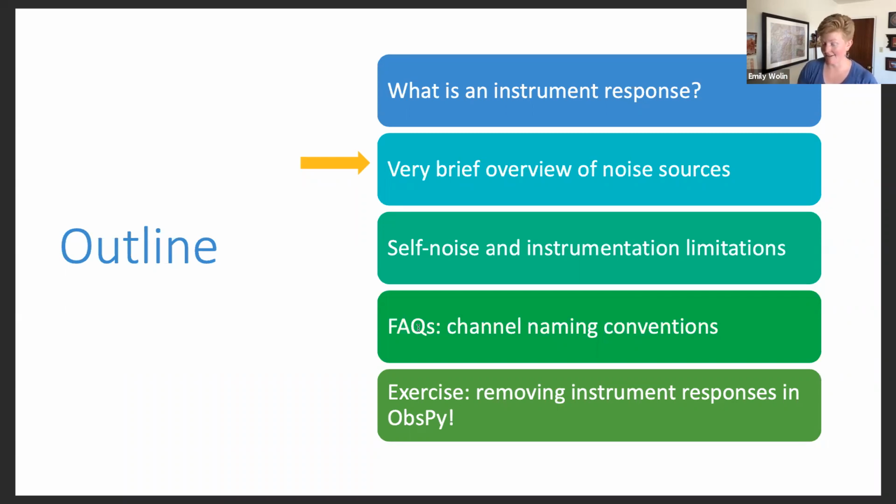It can vary slightly depending on what source of metadata the person is using, right? If the manufacturer updates their instrument response, you might get slightly different poles and zeros because they're always doing their own testing as well. And even if you have the same digitizer model, say a Q330, digitizers very often have selectable anti-aliasing filters depending on your desired application. So just because it looks like the same digitizer does not mean that the settings for the anti-aliasing filters will be identical. Again, that's something you want to be aware of if you're working near the Nyquist frequency. Less important if you're looking at, say, 10-second period data for a station that's sampling at 20 or 40 or 100 samples per second.